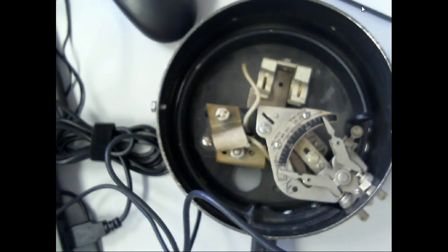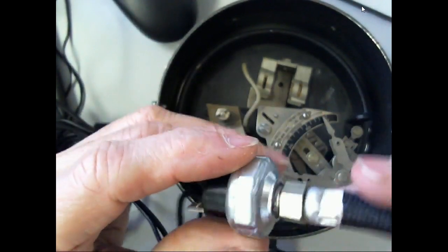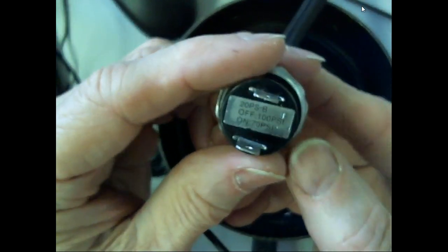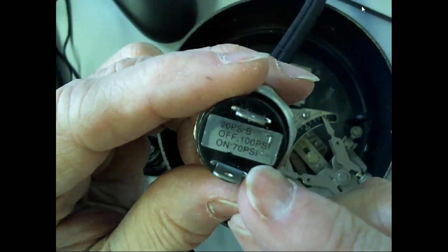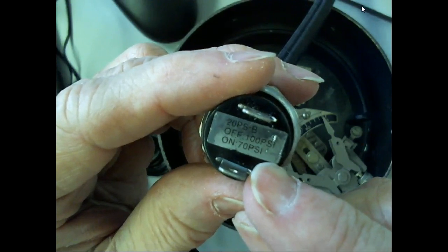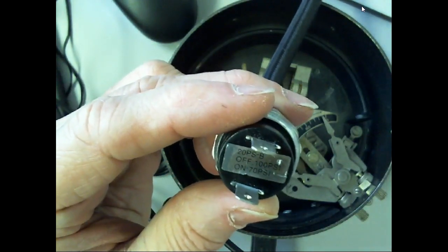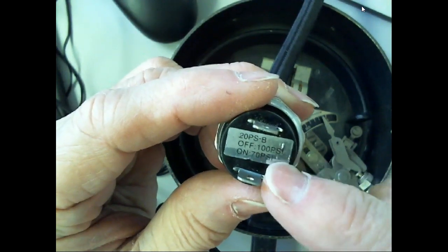We do have solid state pressure switches, but on our diagram it would all use the same symbol, right? You understand? This is a solid state. This came off a compressor. So this has two switches in it. So it turns off at 100 psi and cuts back on at 70 psi. So we have a deadband, or we call it a hysteresis, that we can set. So this is pretty standard for a home compressor.